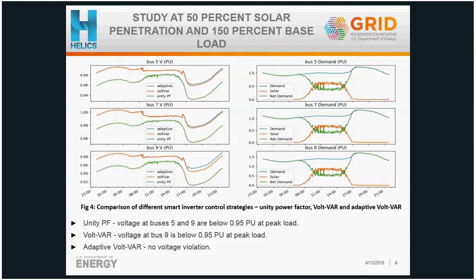But the core simulation framework allows us to do two things in particular. One is it allows us to study the voltage dependence of loads. If I set a different voltage at the PCC, point of common coupling, then the total load injection is going to be different, right? So that is number one. The second one is it allows us to evaluate any control strategy that we have with greater detail. Because if we model everything as a spot load, then there's really not much we can do with control, right? So those are the two things.